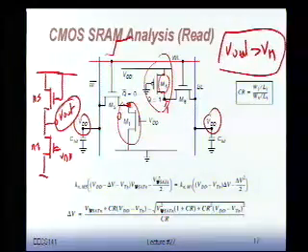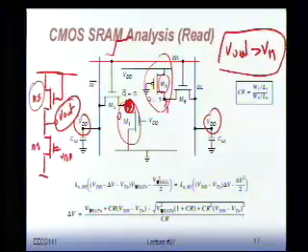We want to make sure that when we apply this waveform here, this node will never go above VM. If it stays below VM, you're going to be fine. You remove the input, and the gate is going to perfectly go back to zeros and ones. So that's the necessary condition. Bottom line is that it will only happen when M5 becomes fairly large.